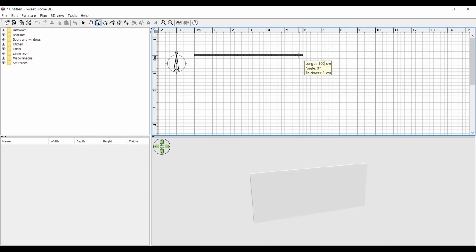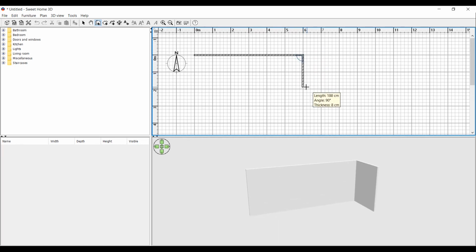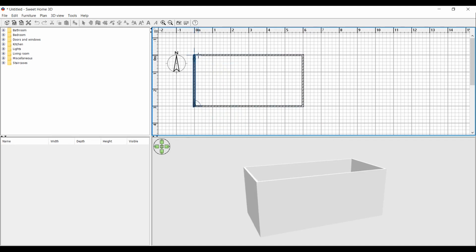At the end press the enter key. And for the width I want it to be 300. Enter. Here you won't need to type the line length, since I have a guideline that these two lengths are equal. Click, again click, press the escape key, it's okay.